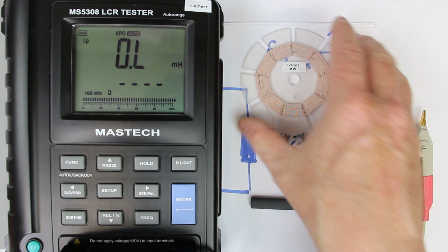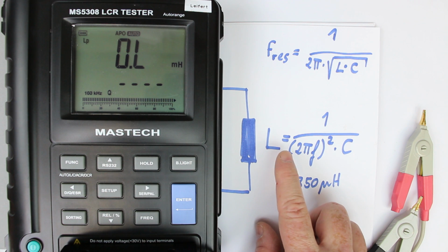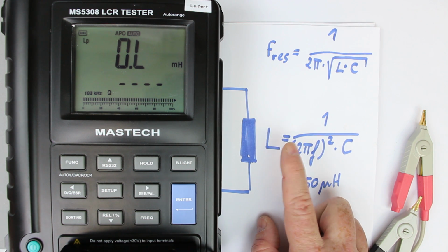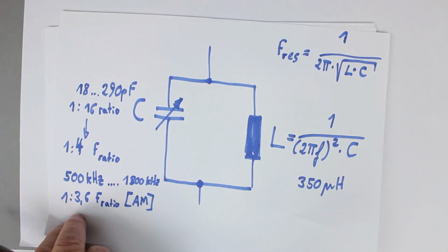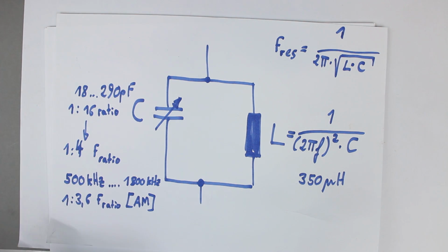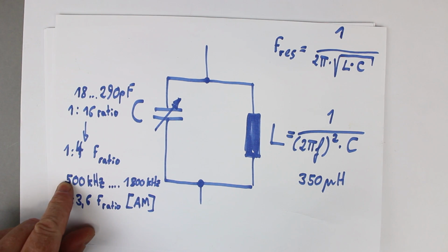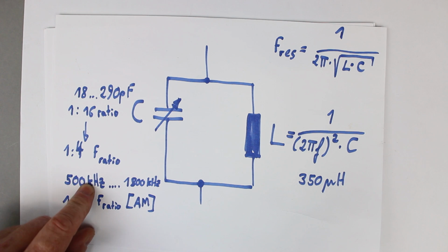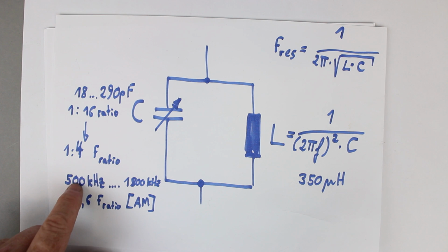Now, if you recalculate it, you will still get quite a difference. That's why we made some generous assumptions about our frequency range. In fact, due to some tolerances, it only has to start at 525 kilohertz, and we still can add some little extra capacitance if we don't reach the lower end of the AM band.